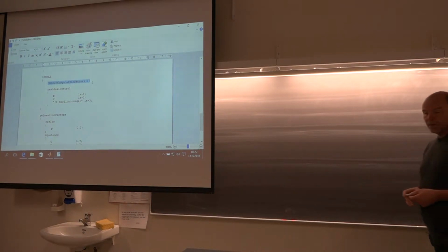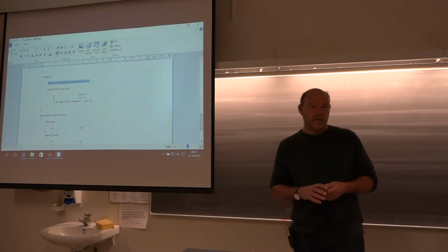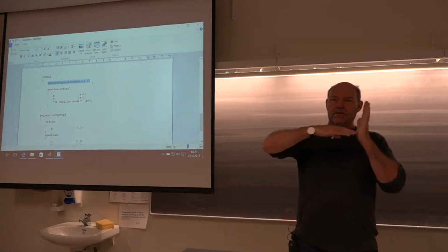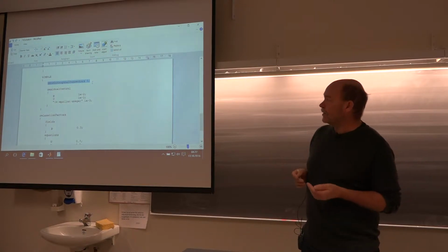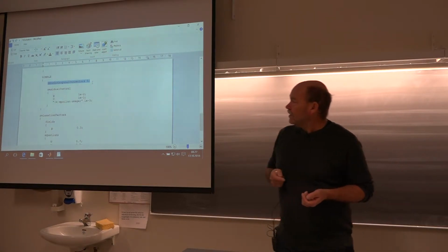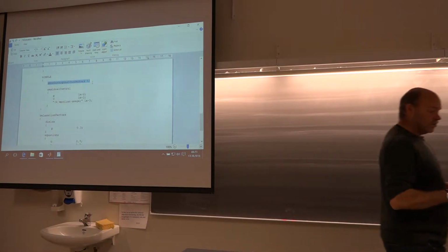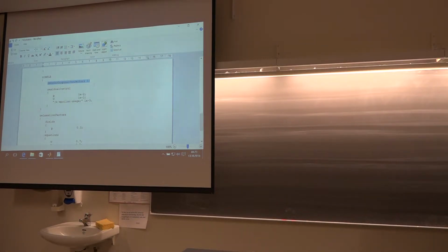That was the number you could play around with for the case where the mesh is not at 90-degree angles. If you have some different angles in your mesh, then you should increase the 0 there to 2, 3, something like that. Also here, relaxation factors. I will try to explain all this today.